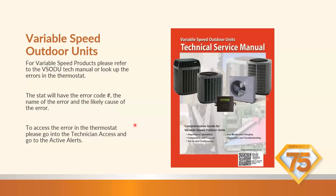If you go to the thermostat and you go into technician access and go to the active alerts, it's going to give you the error code number. It's going to give you the name of it, tell you what the problem is, and it's going to tell you the likely causes, what could cause this error code to happen. Sometimes there's multiple reasons that could happen, 3 or 4 or 5 things. The thermostat will tell you all those things, whether you're using a 1050 or an 850 thermostat, or if you're on even the newer stuff and you've got the new Link thermostat, they're all going to have those error codes in the thermostat. They're going to give you the causes of them.